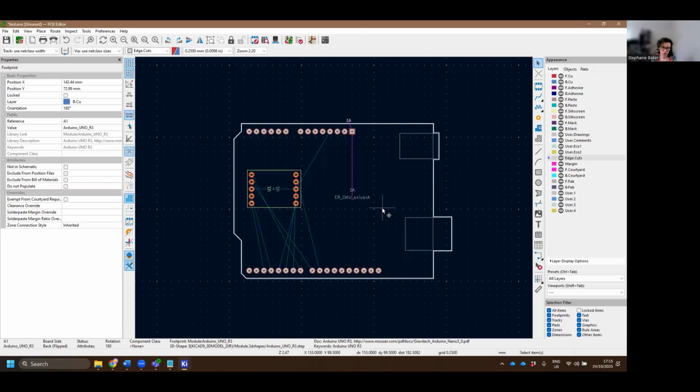Now, in your actual assignment, you're not going to have to create anything as complex as a 7seg LED. Probably the most complex one you'll have is your microphone. So for your microphone, if you can't find a footprint that makes sense for you, there are a few available that probably will work, but that might be one that you want to design yourself to get it more perfect to the exact shape of your mic. For anything else, really, you would expect to find a pinout that works and a footprint that works.